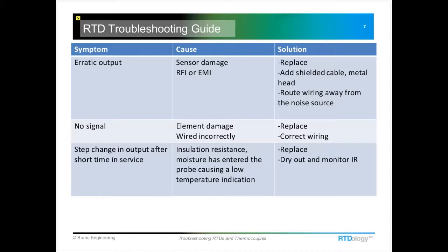So anyway, they had the power cables and the RTD wires all run into the same junction box on the wall, and that's where the interference was coming from. So the fix there was to separate those two and have a separate junction box for the instrumentation and one for the power going to the mixers and the pumps and other things like that. So that turned out to be a fairly easy solution, but took a little bit of time to separate out the wiring.